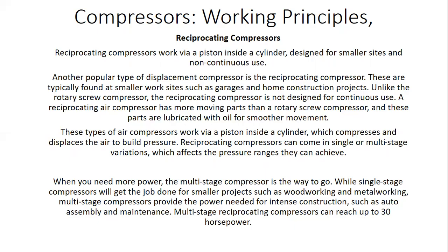So reciprocating compressors can come in single variation or multi variation. That means you might have a compressor that has only one piston, or you might have a compressor that has more than one piston working together. When you need more power, then you will have a reciprocating compressor that has more than one piston, which is now a multiple stage compressor.